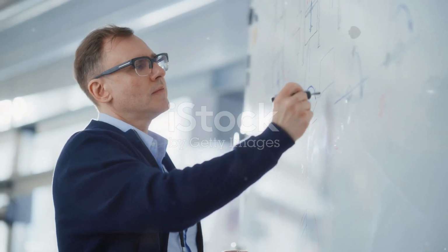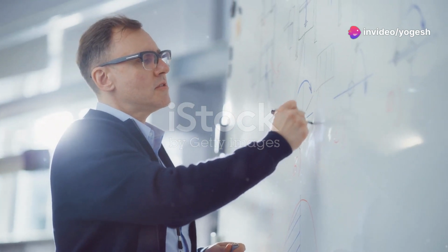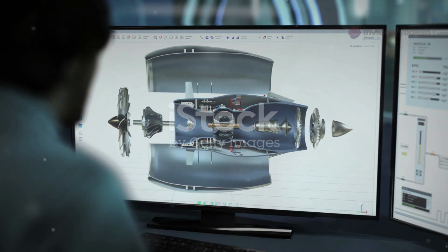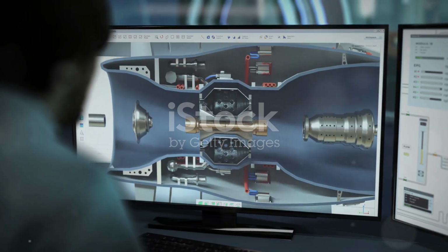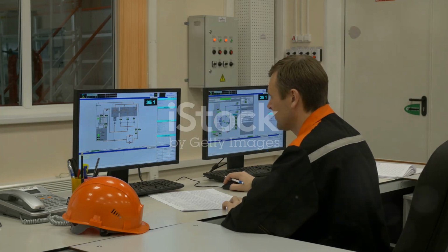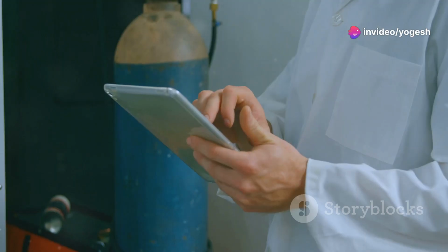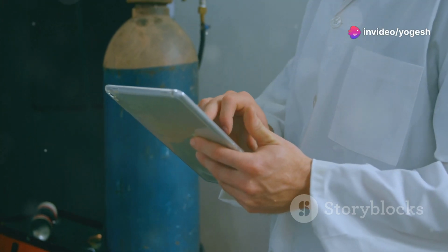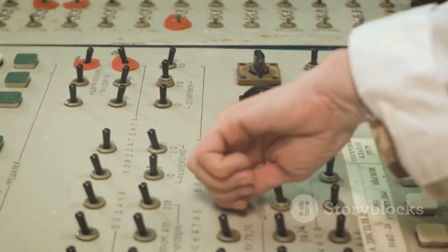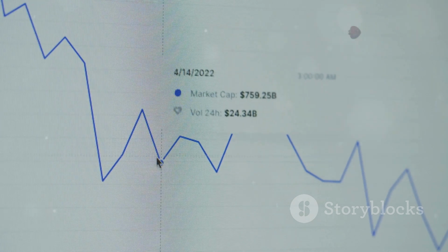Section 5. D for derivative, predicting the future. Now, let's explore the D in PID. This stands for derivative. The derivative component is all about the future, in a way. It looks at how fast the error is changing. It calculates the rate of change of the error. If the error is changing quickly, the D controller provides a strong response. If the error is changing slowly, its response is weaker.